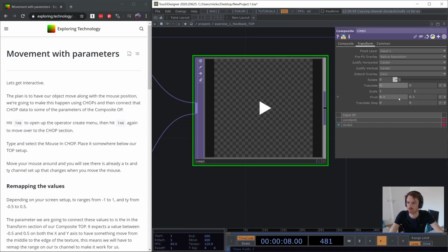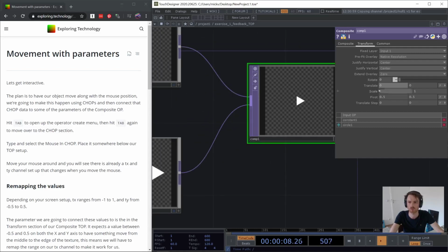Now, one of the things that's pretty handy if you're using a mouse in TouchDesigner is that you can middle click and then hold on these numbers, and then this little window appears, this one with 10, 1, 0.1, and so on. This is a way to dial up and down variables. So I can go into, for example, point 1, that's already here. If I drag to the right, you'll see that my object is moving around on the x-axis just by moving left and right while I'm holding the middle mouse button. So this is just a quick way to change parameters.